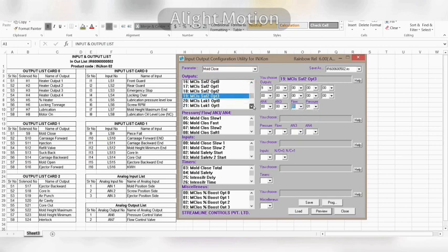If we want to turn on more than one output at the same time, we have to define more than one output in each option. In each option, you can define up to 10 outputs. According to the requirement, you can see output number 6, locking of the mold close, is defined in our wiring list. That is, my 2 valves should be on at the time of locking, such as mold close number 9 and locking tonnage number 6. So we have to turn on number 9 and number 6 in mold close tonnage.